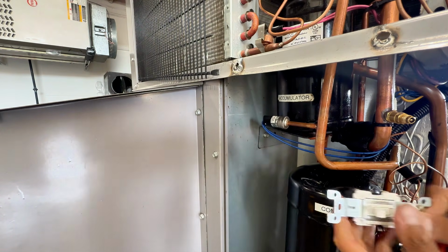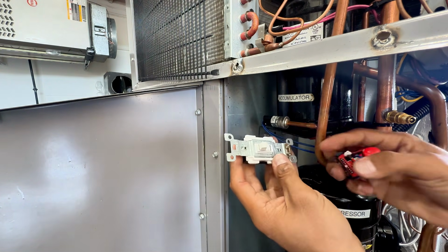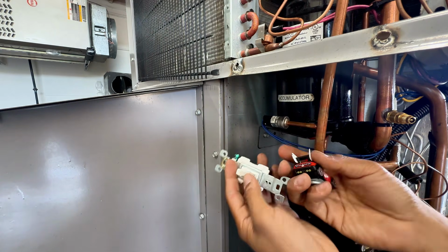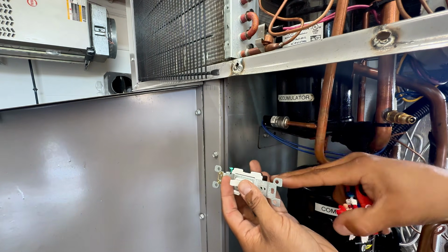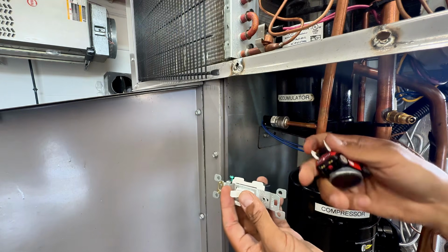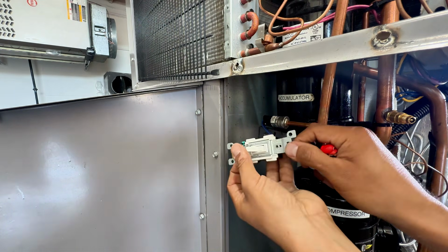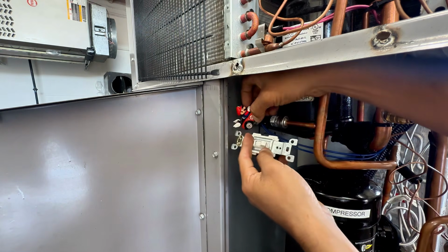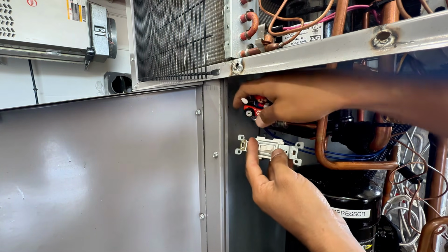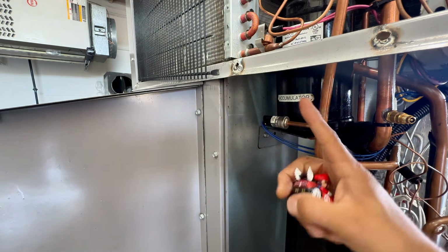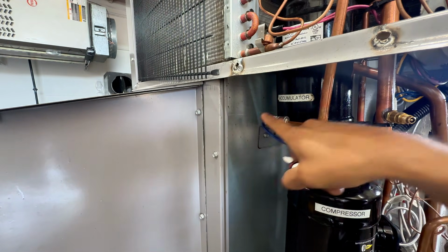And so that's just the switch. It's just a bridge. So right now, let's say a low pressure switch, if I don't have low refrigerant and I don't have a dirty filter and my pressure stays good, then good, I can go through. The bridge is good. It's closed. So Mario goes in and goes out. 24 volts goes in and then it comes out.